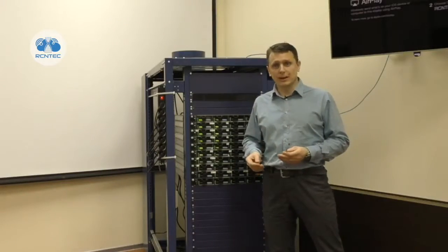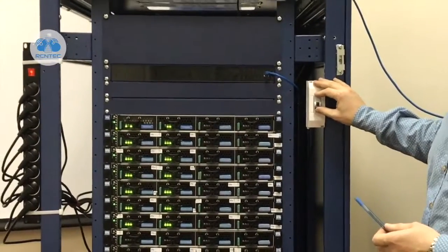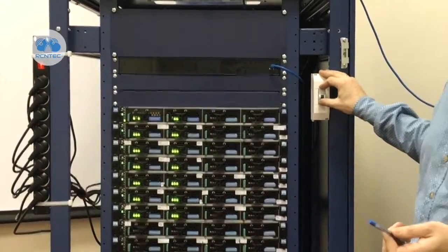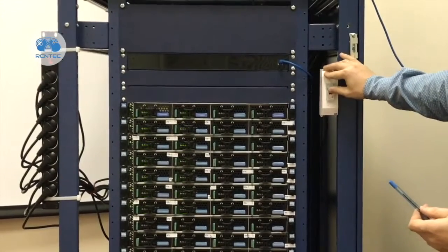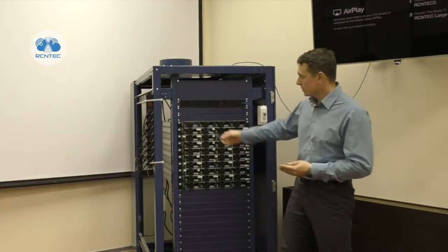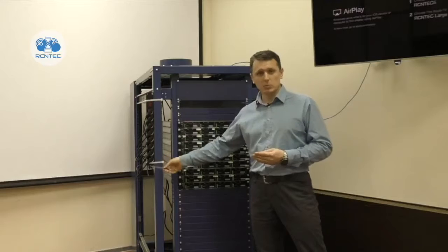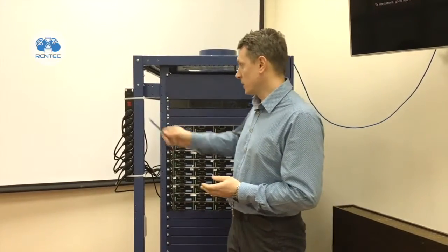Let's simulate failure of one of them by simulating a short circuit using the special device created for this purpose and see what's gonna happen. As we can see, failure of the single consumer has led to powering off of all devices powered via this power strip. Why does this happen? Because in case of a short circuit, either fuse of the power strip blows or the circuit breaker disconnects power of the feed.